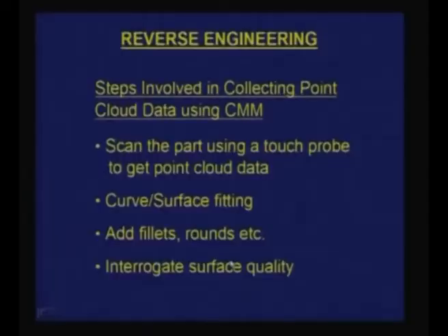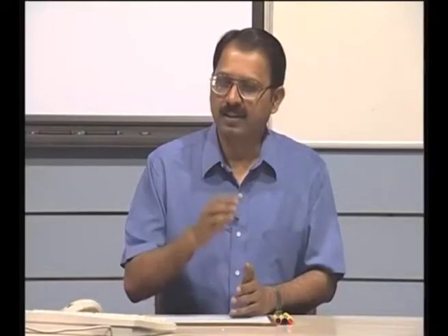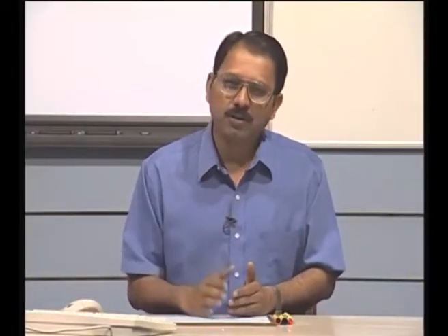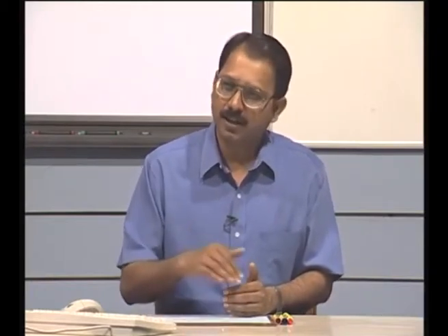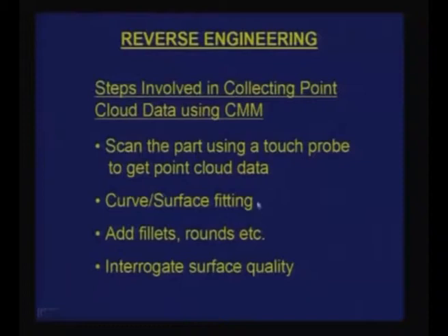And you also interrogate the surface quality, how good this fitting has been, whether the surfaces which you have constructed from point cloud data itself have a large error, or whether they truly represent the point cloud data, and whether there are any gaps. Or interrogation also includes finding higher levels like slope continuities, curvature continuities of the surface, whether they are met or not. All those things are done as a part of this.